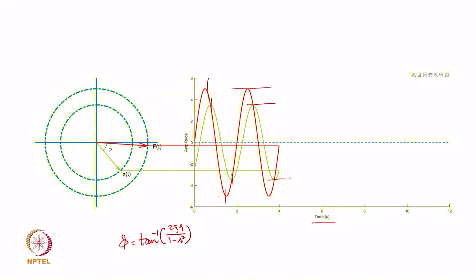So, maybe we will be interested in knowing the peak to peak or response amplitude; whether it lags by 20 degrees or 40 degrees may not be so relevant in general, but it has its own role, particularly in some applications, like when you are trying to balance a rotor or in balancing processes, where those phase values would be of significance. And it helps in understanding the vibration phenomena better, as we shall discuss in the base excitation case.